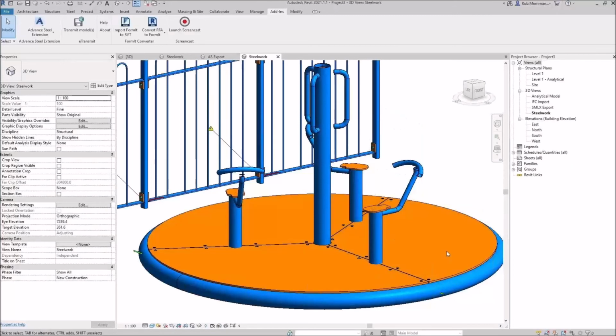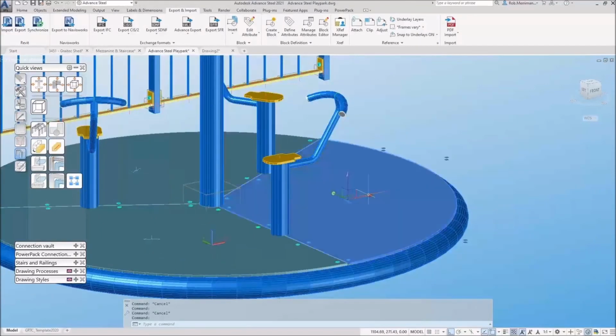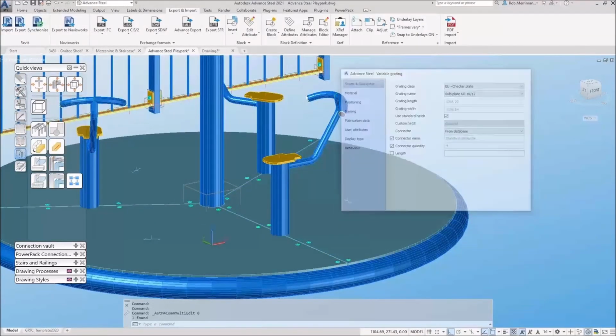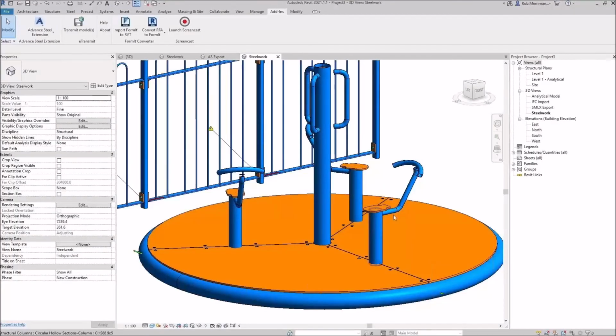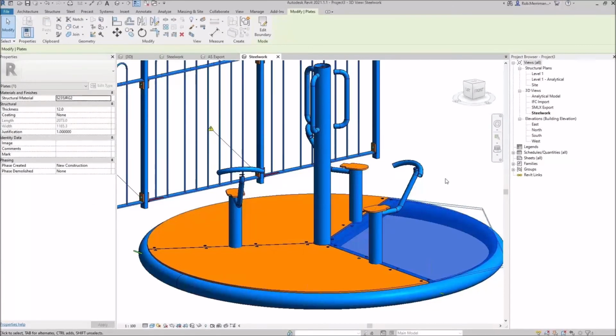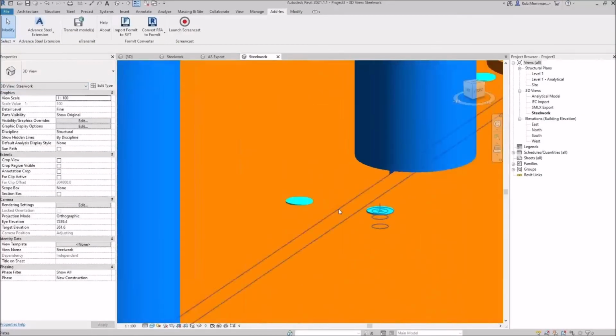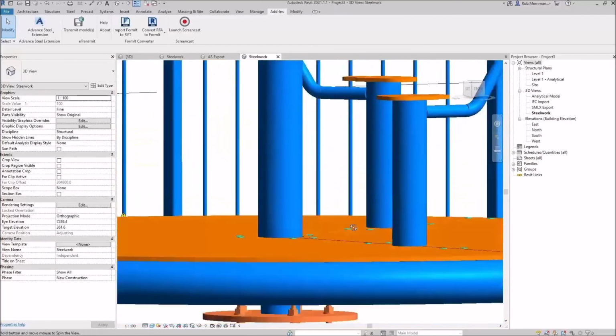The Advanced Steel grating, so in Advanced Steel, we have this grating, and it is an actual Advanced Steel grating. And again, in Revit, there is nothing in Revit called grating. They don't have functions to create gratings as we do in Advanced Steel. You always have to remember with these imports and exports, they are different programs. So what it has done is it has imported it as an Advanced Steel plate. But we still have the geometry, the shape is correct, the bolts are still bolting through, we've still got the gap in there that we created last week.